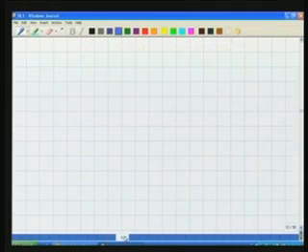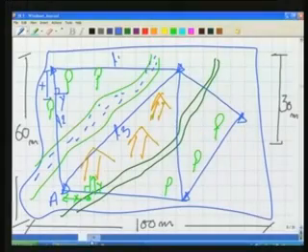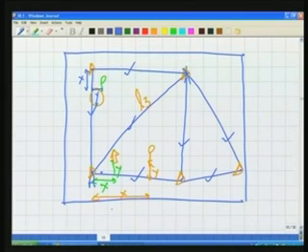The second one is, now here we carried out all these lengths and we plotted them here. Is there any other way? One way is redundancy, we introduced redundancy. But is there any other way of checking the accuracy of this system? Well, one more method is possible, and that method is what we call a check line.